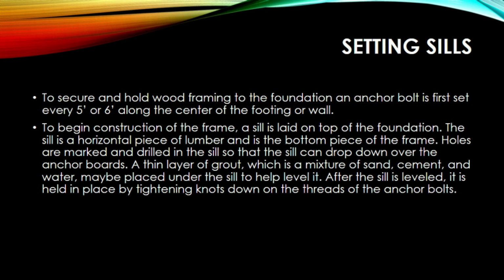A thin layer of grout, which is a mixture of sand, cement and water, may be placed under the sill to help level it. After the sill is leveled, it is held in place by tightening nuts down on the threads of the anchor bolts.